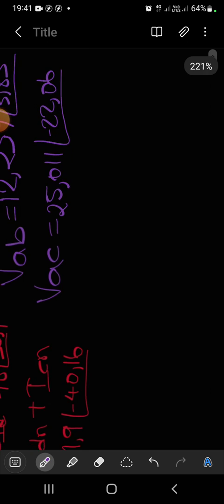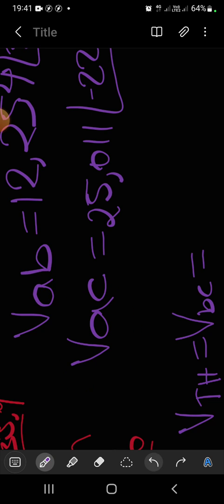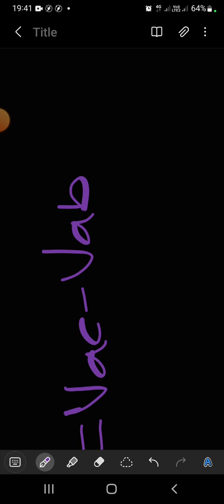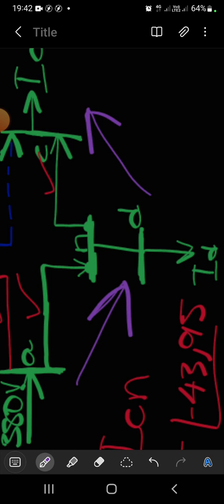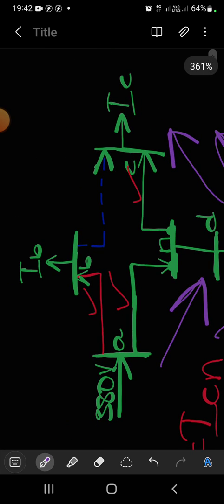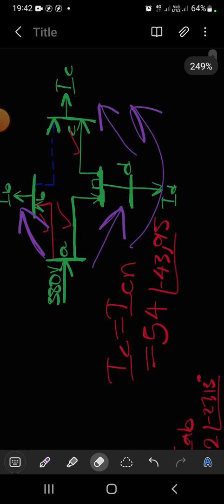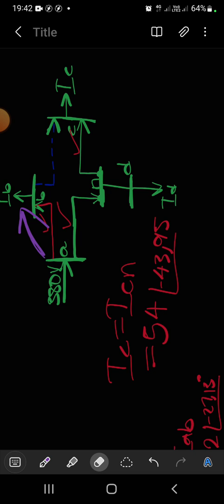From there, remember, we have to find now VBC, which is the difference between the top and the bottom voltage. I hope you are aware that this is the bottom and this is the top, right? So that's VAC minus VAB. Why do we have subtraction? I'm going to repeat this again. You see, VAN is heading in that direction, and is going the same direction with CN as well, right? This is counterclockwise, but then AB is going in the opposite direction. This is why you have subtraction, right? I want you to be able to see that and not cram it, but I know you saw it.